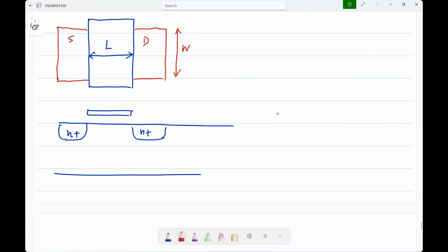Okay. And because of that, a lot of even the familiar parameters are described only with those two dimensions, because this third dimension you don't have any control over. Okay. You can't control how deep this is. It's a property of the technology. It's just given to you. Okay. So in the MOS transistor, it's very clear. Anyway, we had W and L, and when you go to design, you will need to know the rules about how long this must be and so on. Okay, there will be some minimum constraint. We don't have to worry about it now. Okay,